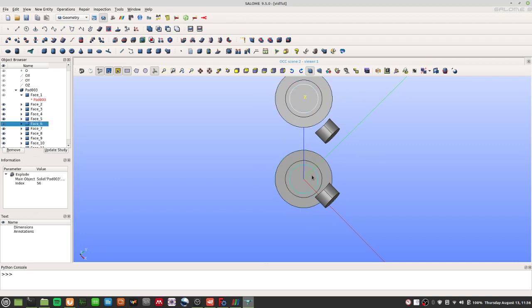The tube side here, all you see are two faces of the inner tube, but there's no surface describing the interface between this inner tube and the copper. Likewise, there's no interface between the outer shell and the copper. All of that you'll have to include yourself. You'll have to start making all of this in Salome. Okay, so that's phase 1.